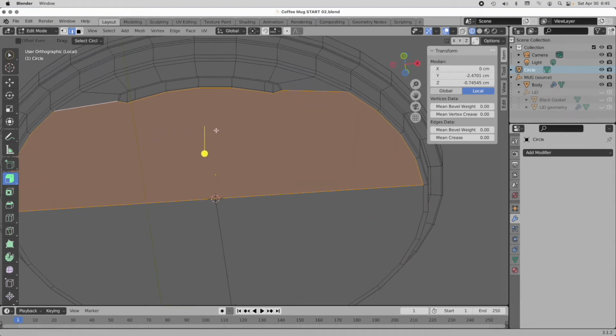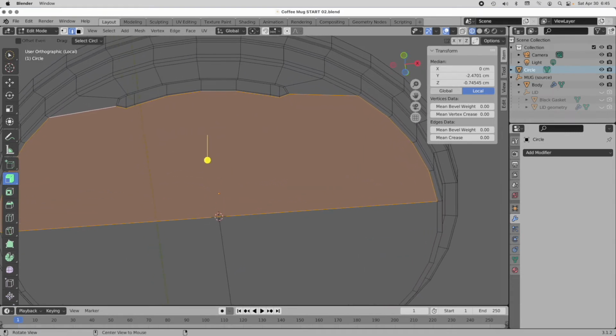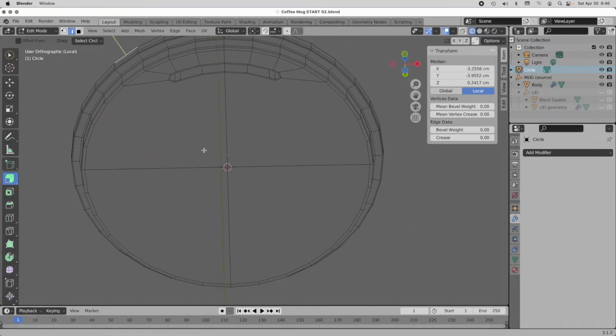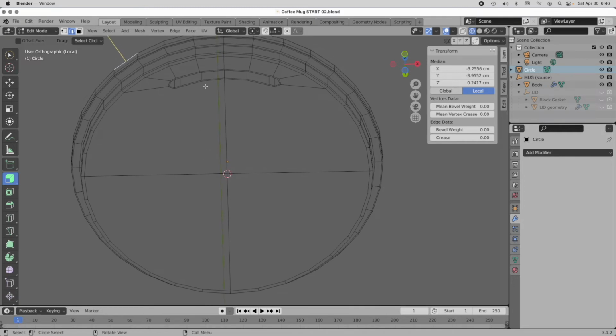And then to close this off, we're going to be subdividing it. And we really want this to be diced up in a really appropriate way for subdivision surfaces. So I'm going to press that K key again. We're going to come right there, click, click, hit return. So we've essentially just established the basic symmetry. And what I want to do is I really want this to be connected.